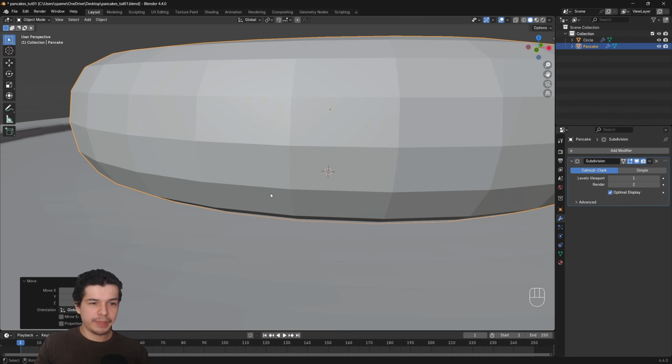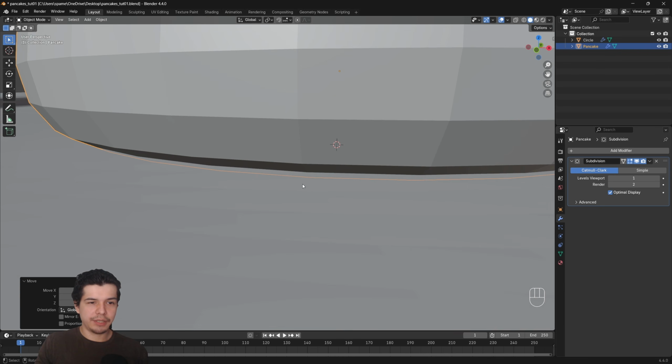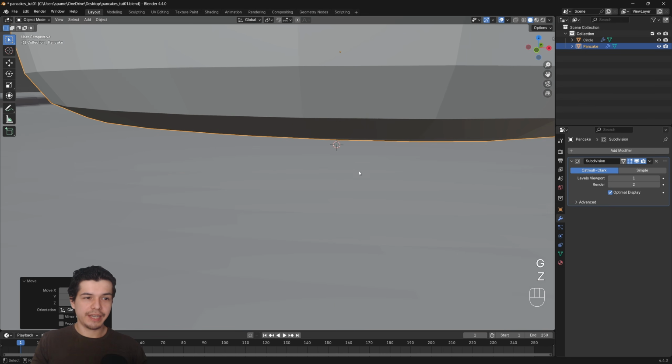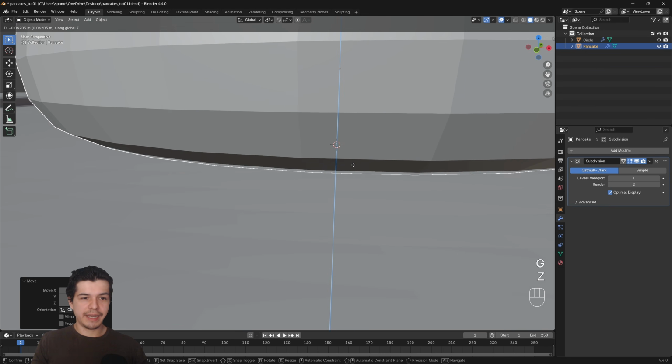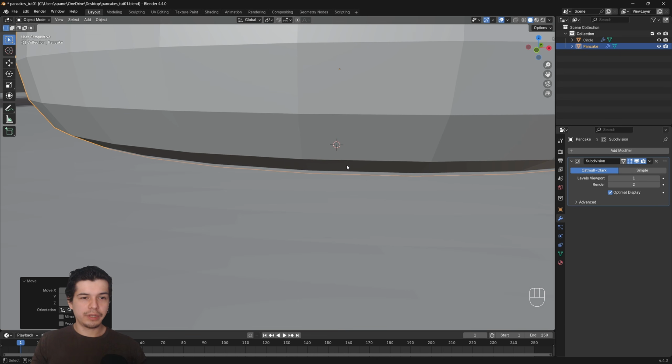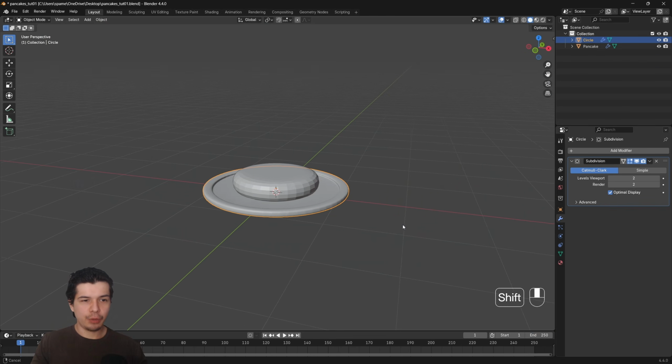down. If you zoom in, you can see this outline of the mesh, and if you see just the outline and you don't see the mesh really, it means it's inside something. And I want it to be slightly inside, so it's either like this, or you put it inside. See the changes? So put it a bit inside so that when we use lights, there's not shadows as if it's floating or something. Now we have to duplicate these.